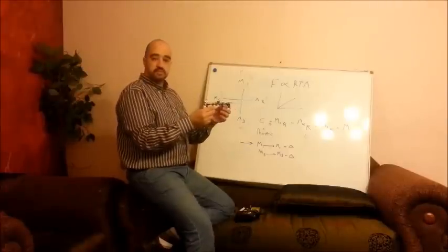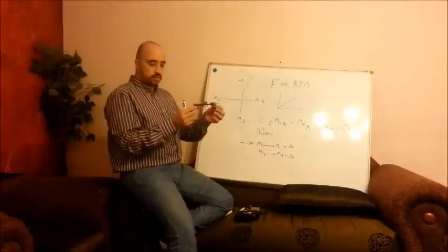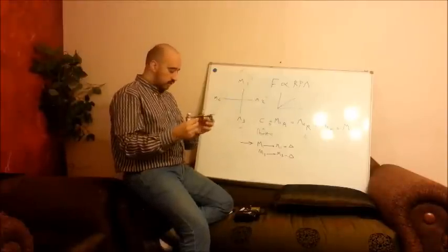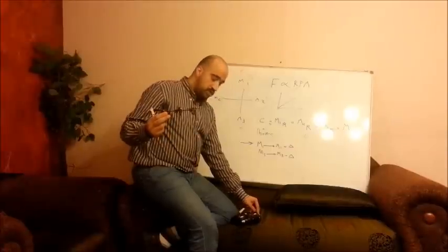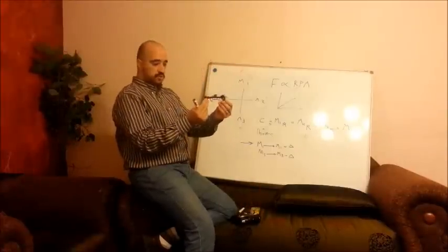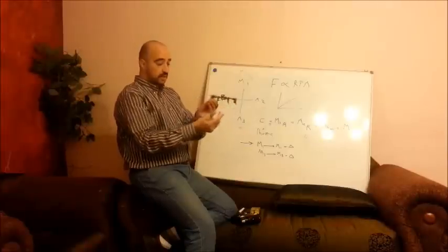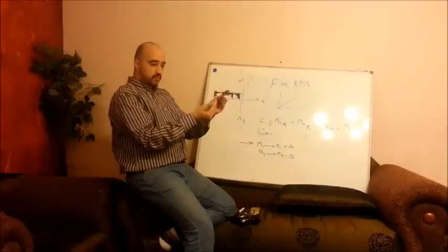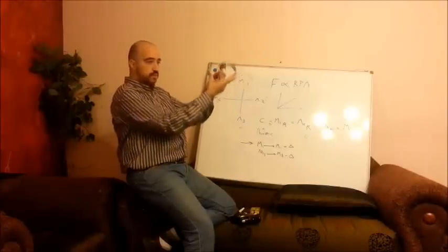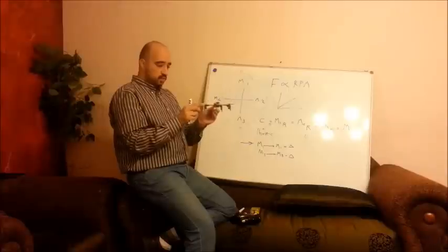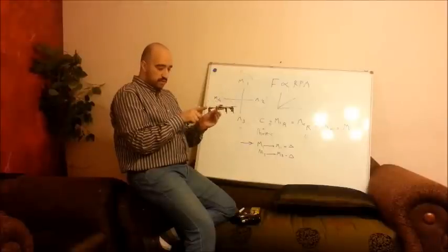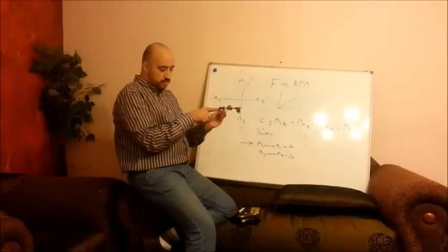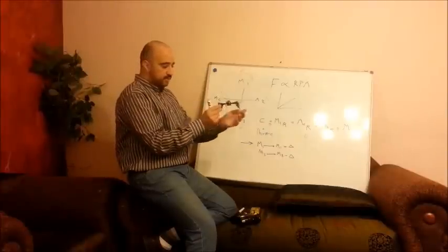Now let's consider the third type of motion for a quadcopter, which is the rotation in the yaw. When I change the rudder here, the quadcopter moves like that. And this is strange because the only force we have is a force that pushes this quadcopter vertically. So how can we produce a force that pushes this quadcopter like that and make it rotate?